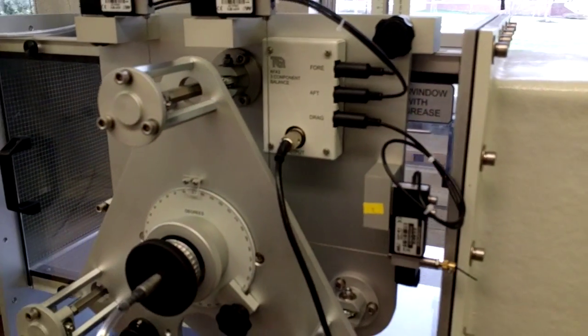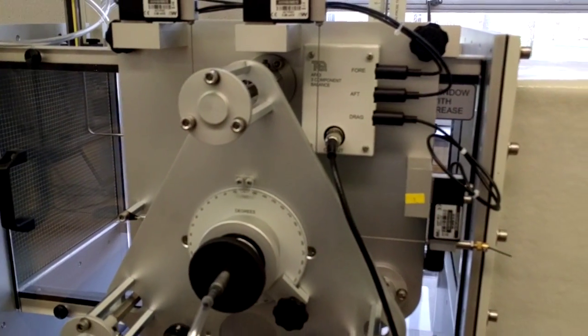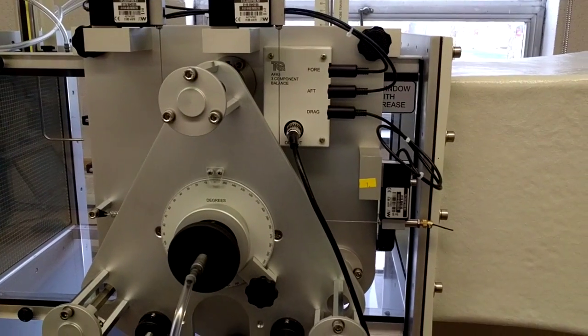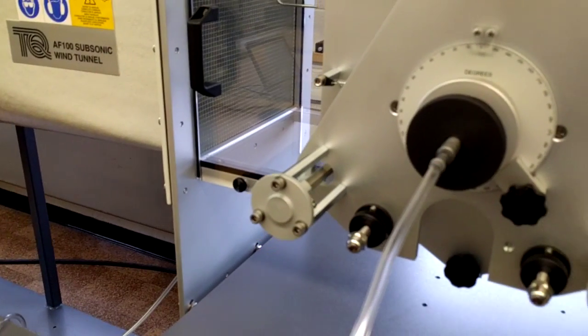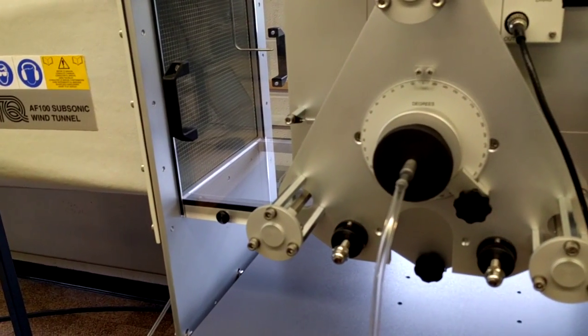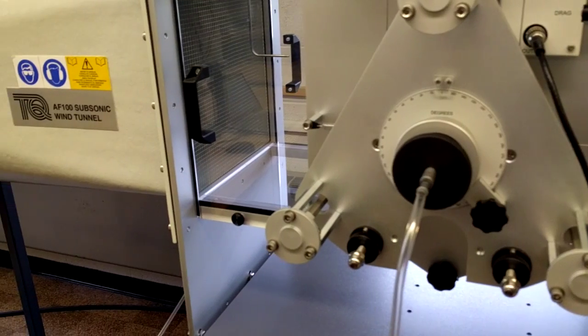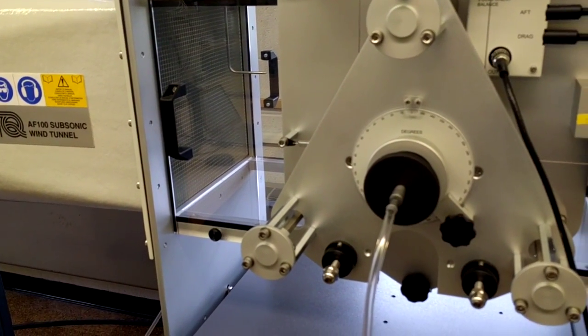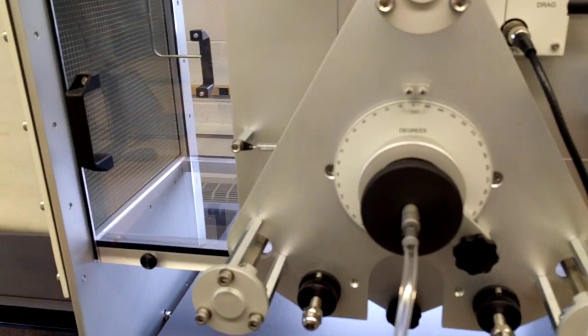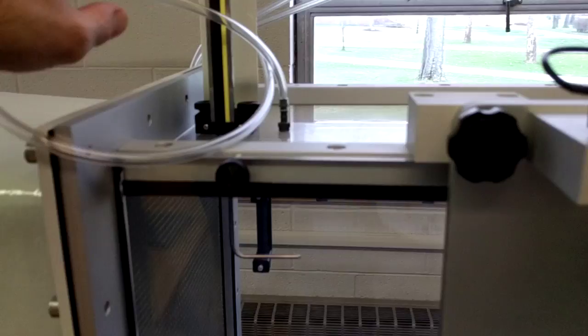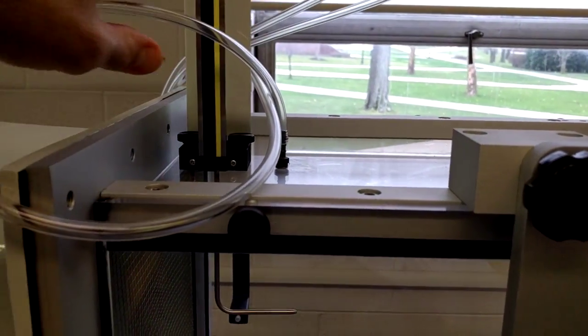The cylinder itself has, on the front, although you're not going to be able to see it on this video, a little tiny port. Starting off in the experiment, air flows against the port. The port has a tube connected to it that goes to a digital manometer on the control panel. The digital manometer measures pressure difference. In this case, the pressure difference is measured between the pressure measured by the port and the pressure measured by the edge of the test section.